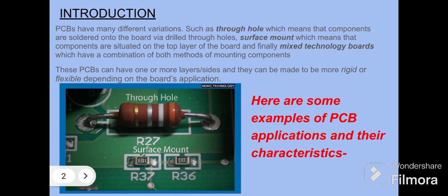These two different types have their own advantages and disadvantages, but personally I use through-hole a lot more because I hand solder, and through-hole tends to be a stronger connection, but in manufacture you can easily mass produce more surface mount because of wave soldering.